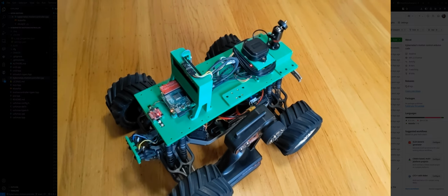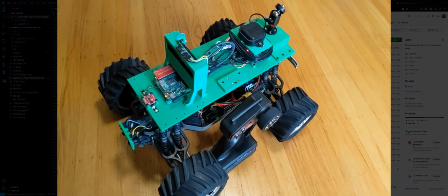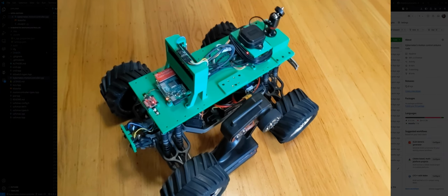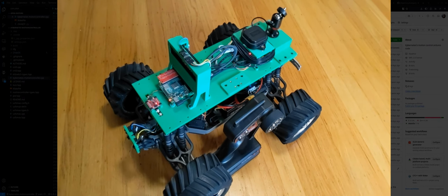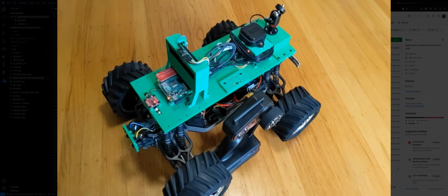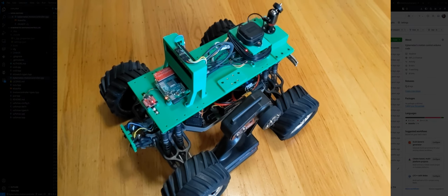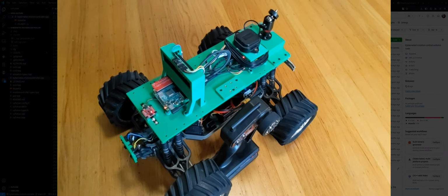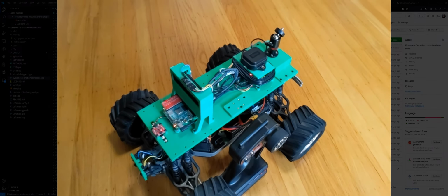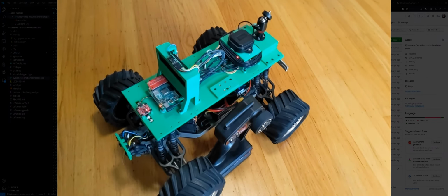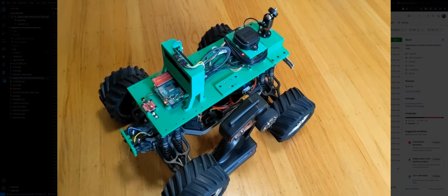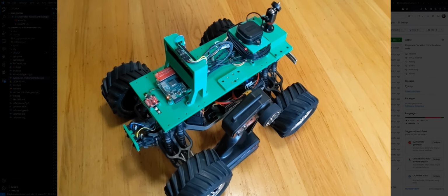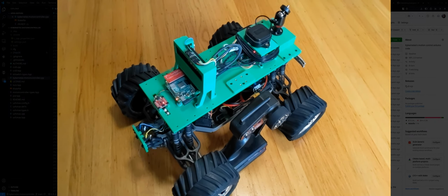But one of the pieces of hardware that I put in that logic power distribution unit was a voltage and current sensor so that you can measure actual power usage by something, both immediate and continuous power usage, or because the sensor has what's called an integrating analog digital converter in it, such that it can measure power usage over time, otherwise known as a Coulomb counter.